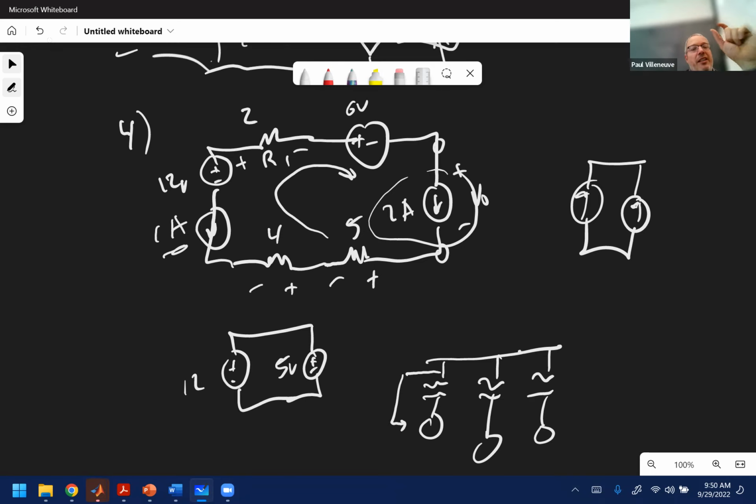So if you wanted to put these two in parallel with each other, what you would do is say, okay, I'm going to set this to 12 volts, but I'm going to make this an adjustable supply so that once I get to a certain value of power output, I'm going to start to back off my voltage because I don't want to damage the unit. So when you actually operate in parallel, things are a little bit different. And so why am I bringing this up?